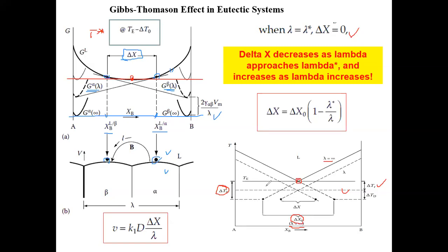Based on this very simple illustration, we know that if you change lambda, you reduce the effective melting temperature and you also change the difference. So this change of difference is proportional to the change of the effective supercooling that you're feeling, and we know that this effective supercooling is related to lambda through this well-known relation of 1 over lambda. That's basically how they're connected.